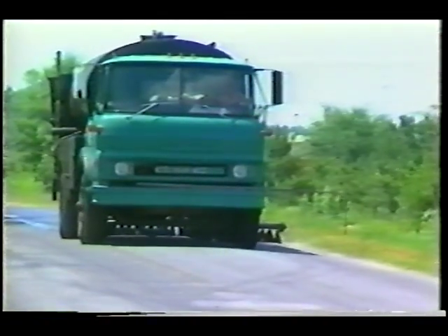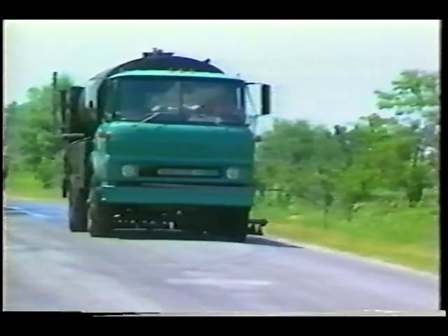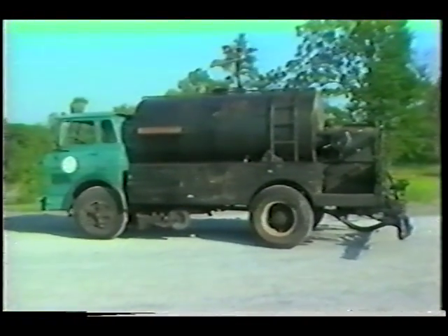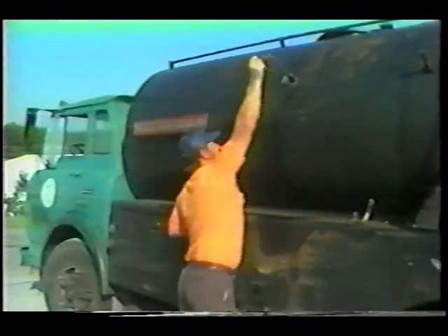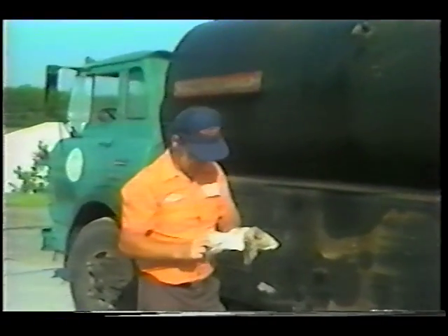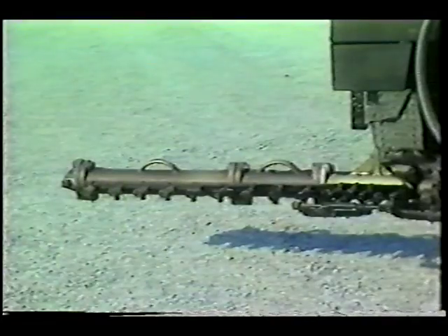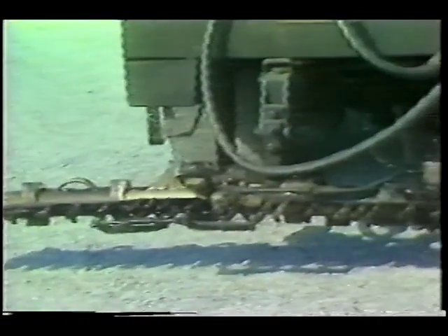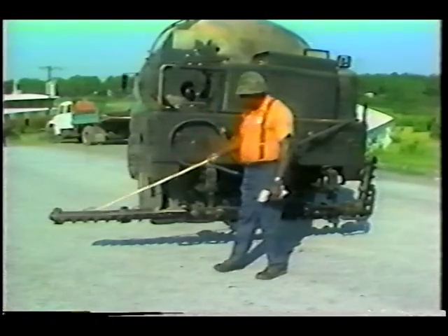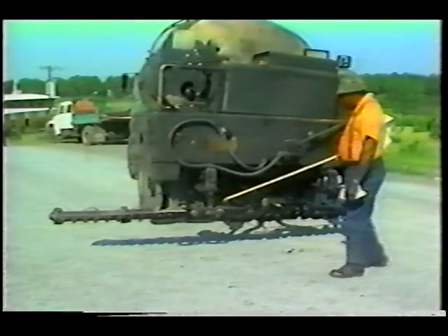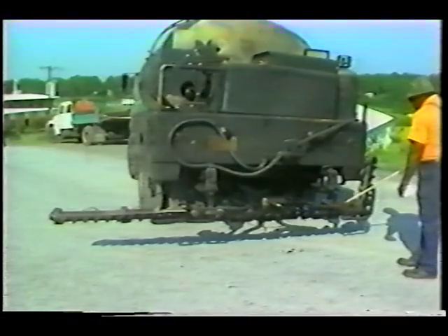Apply the liquid asphalt using an asphalt distributor. The distributor consists of a truck-mounted or trailer-mounted insulated tank with appropriate controls for setting the rate of asphalt application. The tank contains a heating system to maintain the asphalt at the required application temperature. At the back of the tank is a system of spray bars and nozzles through which the asphalt is forced under pressure onto the pavement surface. The distributor tank should be equipped with a circulating system to prevent asphalt from solidifying in the spray bars.